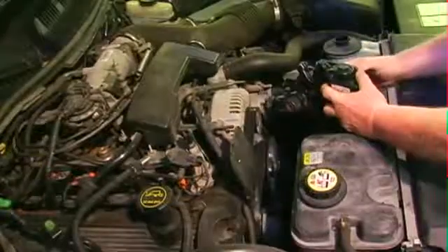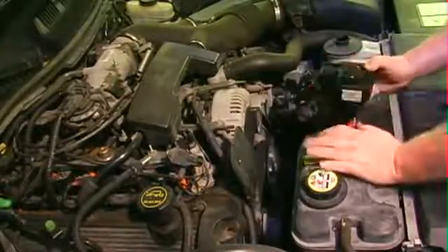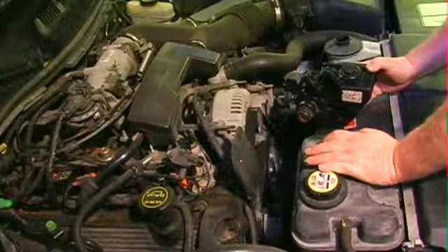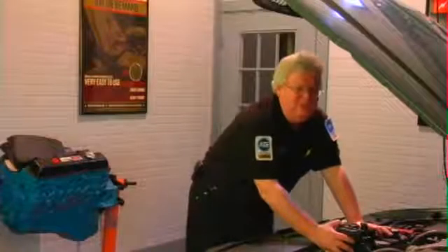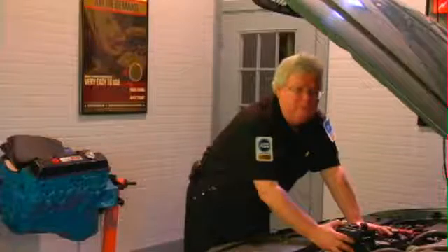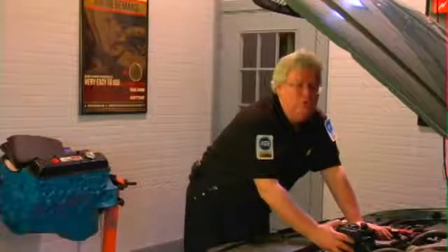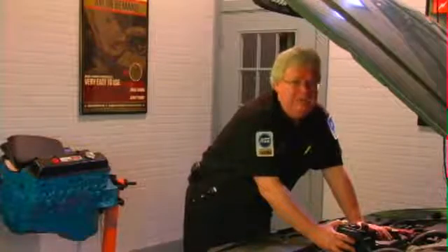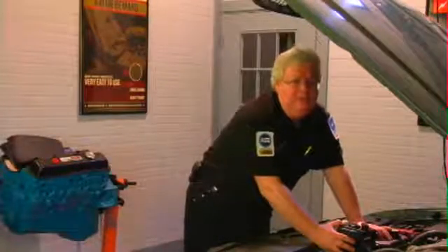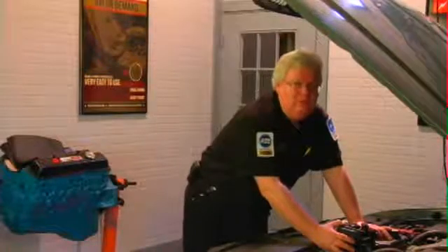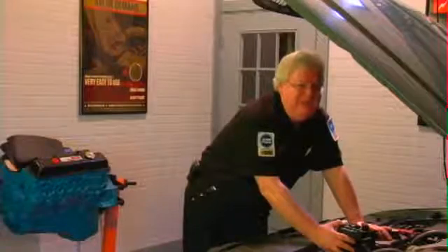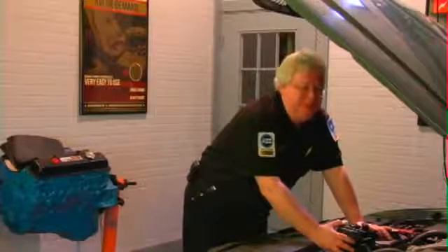So if the pump has a varying amount of pressure, your power steering assist has a varying amount of assist. So when you're in a situation of a parking lot, low vehicle speeds, that's one of the inputs to the module. On General Motors trucks, that module actually may be packaged into something entirely unrelated to power steering, such as their pass lock module, the vehicle theft deterrent system module.